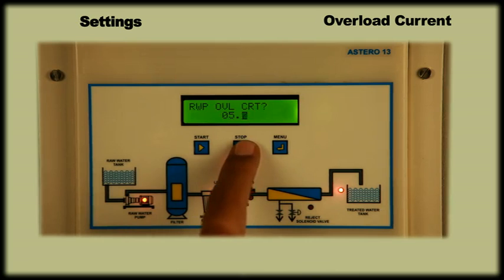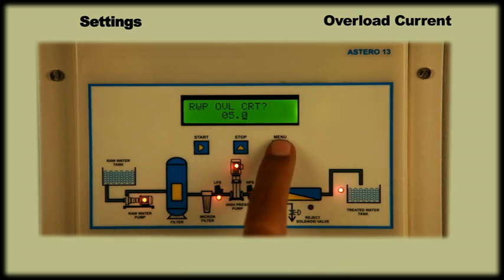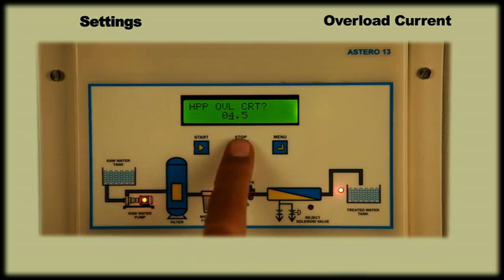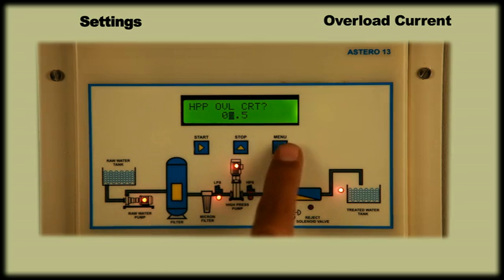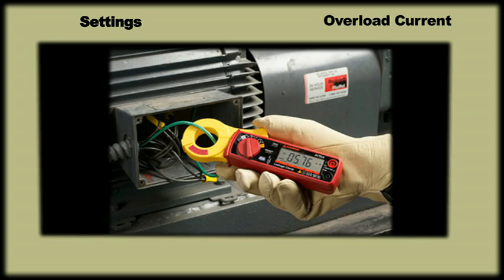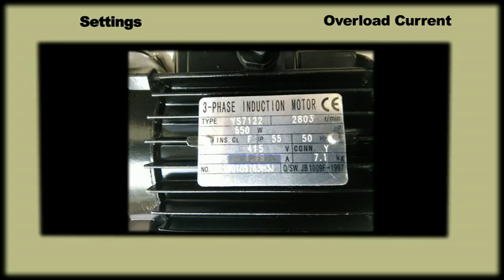After setting the raw water pump current, press menu key. Then the display will show high pressure pump current. Press menu key and display will show previously set overload current. One can change this value using start and stop keys. After setting the high pressure pump overload current, press menu key to save. We recommend to set overload current 20% more than normal running current, which can be checked by using clamp meter or the value mentioned on motor nameplate.